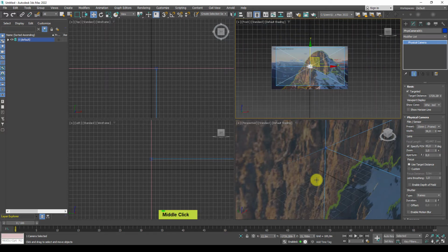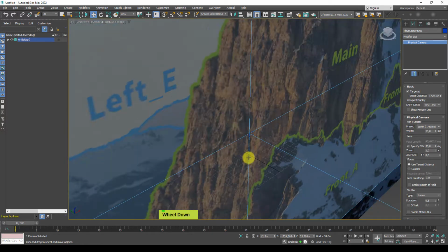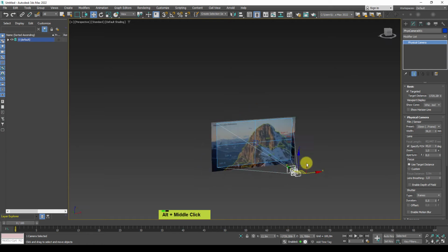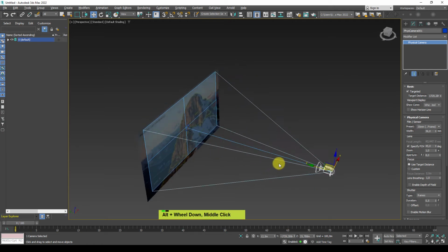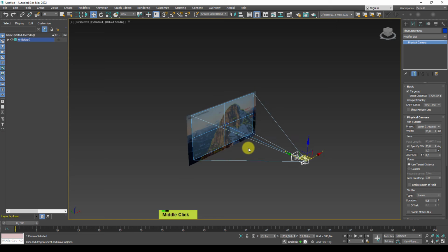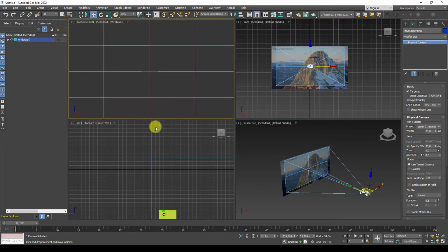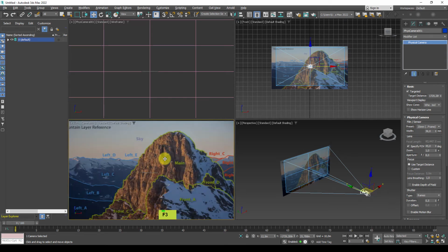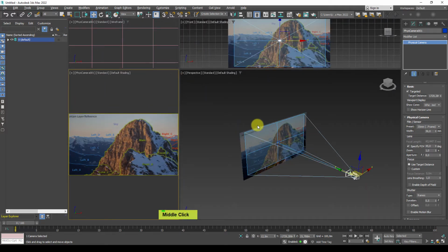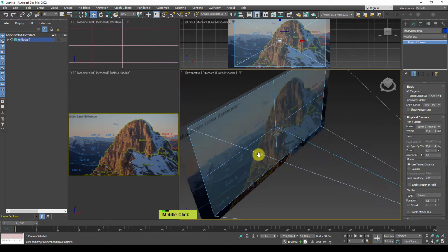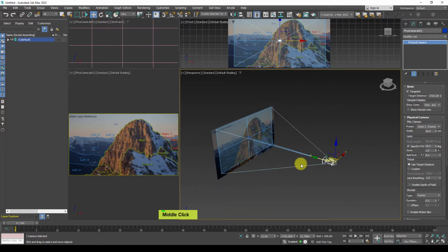I don't want to keep that, and from now on I will use mostly the 3D camera viewport and the perspective viewport. So typically this is how it goes. So we can set a camera here or set a camera here. Function key 3, Shift F, that's save frame, and then we can just resize it to have some room to work around. Okay, so before we go on, let us check that the camera is exactly the same